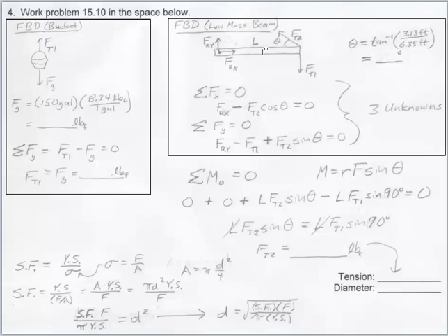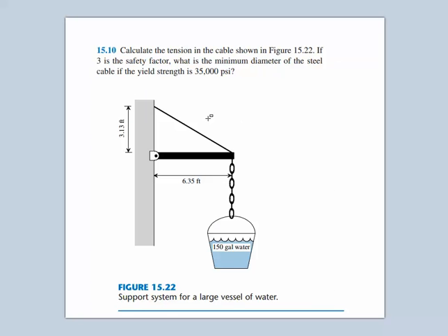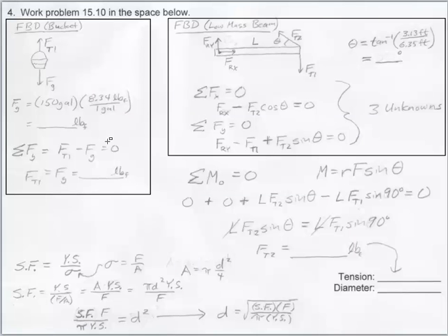body, that would be the beam here. The forces we have are a reaction at the hinge up and a reaction at the hinge horizontally. Just to show you what I'm talking about, there's a force up here and a force over here because of that axis being through the beam. We also have a tension back and to the left. We call that T2, and this is T1, the same one that we saw in the other free body diagram over here. So tension T2, T1.